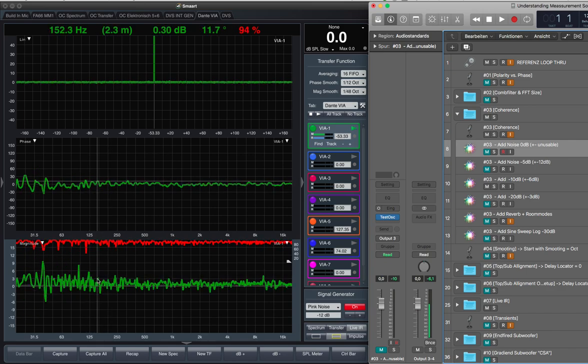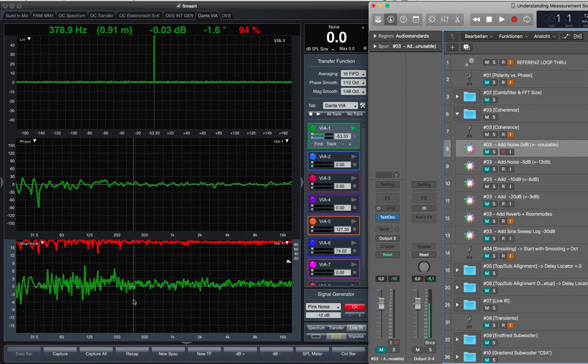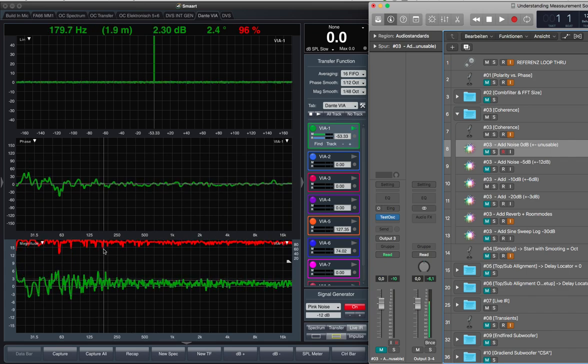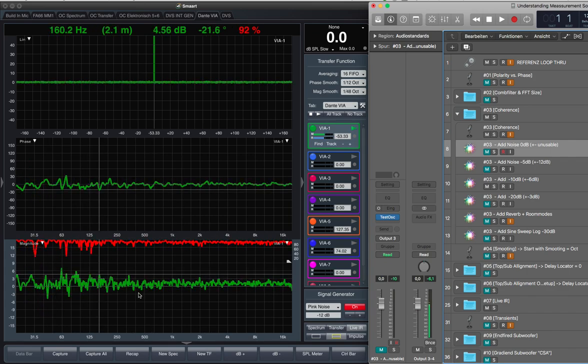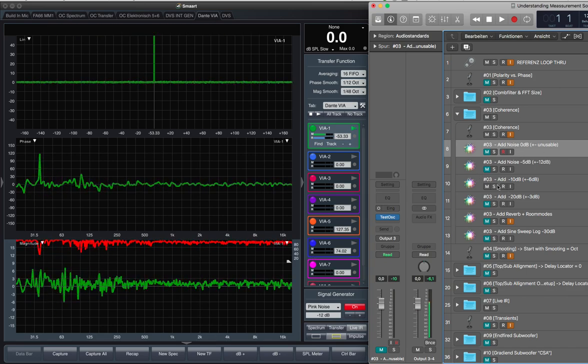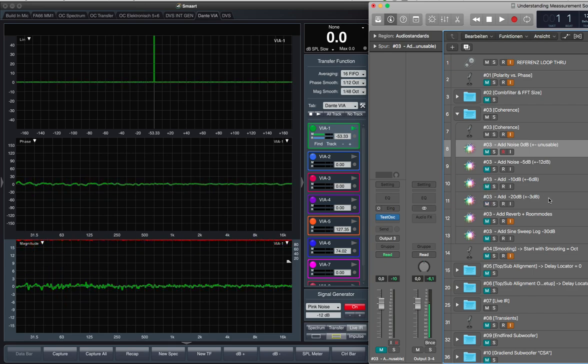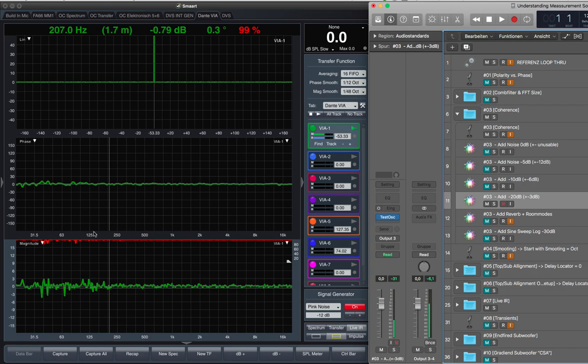And if you think you get a straight line from your straight line speaker in a lab, then you are wrong, because the coherence is not 100%. You have this gezappel here, like Merlin said. The next thing is I decrease the level of the noise to -20, and this is almost perfect. Then you have a coherence here of 99%. It's the best you can achieve in a real life situation, because otherwise your measurement signal is too loud and then you don't have friends in the catering, and we all need them.